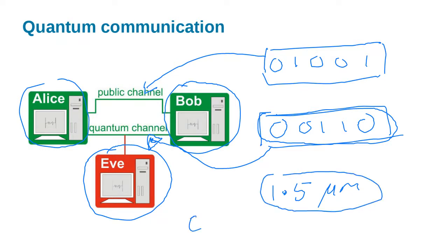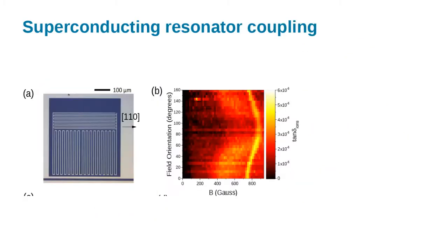So the element erbium is used for amplification. So that's because in the erbium atom there are energy levels that have a separation of pretty much exactly 1.5 microns, which is the wavelength of light that is needed to be sent down optical fiber, because that's where it's got its minimum loss. So what I've been looking at in the research I'm doing is erbium implanted silicon.